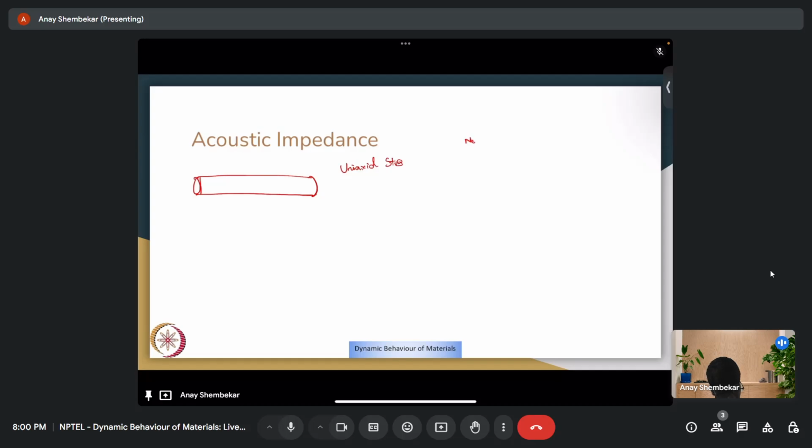Okay, so you have a condition of normal incidence, longitudinal wave, which means theta is 0. Only longitudinal waves propagate. Some force is applied which causes some stress. And if I look at one small thin cross section of the bar, what we see is initially, before the stress acts on this portion, and then after stress acts on this portion, there is a change in momentum. So once the stress sigma acts for a time dt, change in momentum equals impulse.